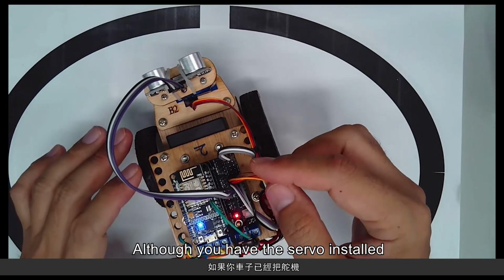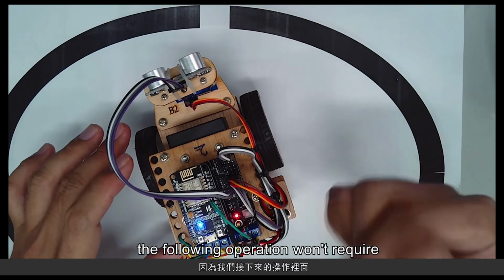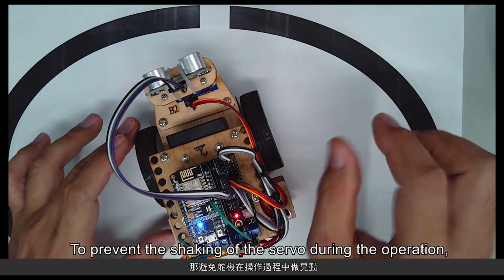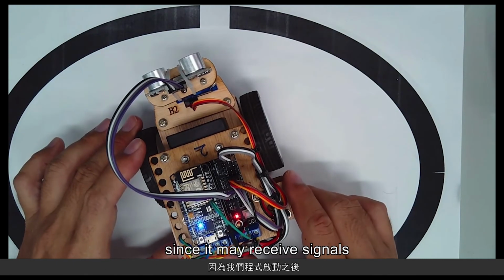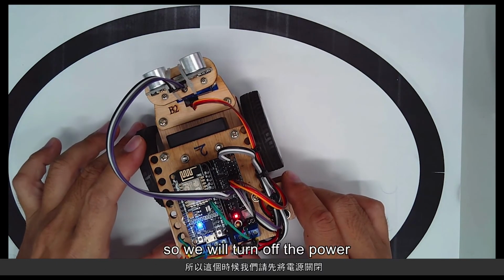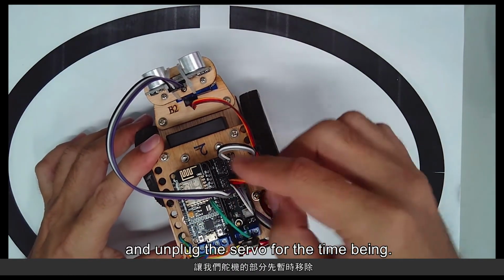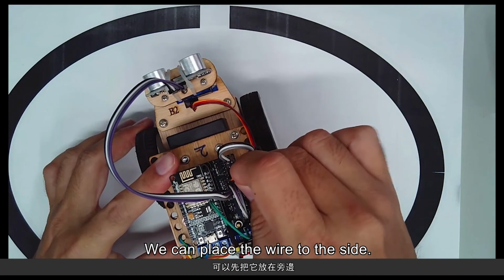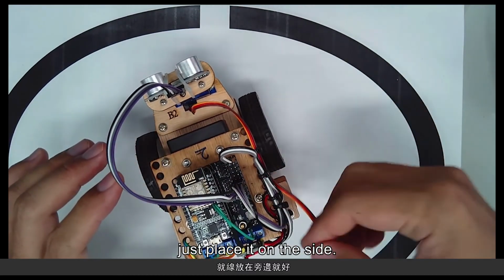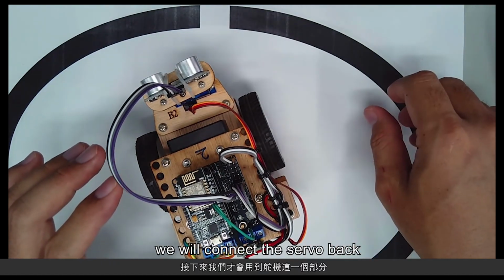Although you have the servo installed onto your vehicle, the following operation will not require the use of the servo. To prevent the shaking of the servo during the operation, since it may receive signals once the program starts up, we will turn off the power and unplug the servo for the time being. We can place the wire to the side. There's no need to remove it completely, just place it on the side. After we've operated up to a certain degree, we'll connect the servo back.